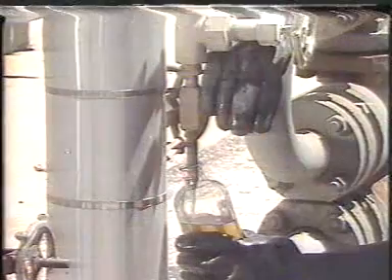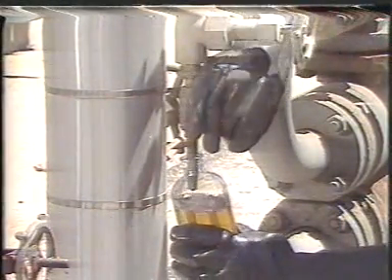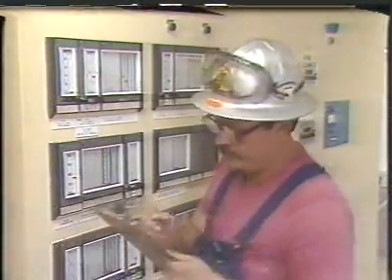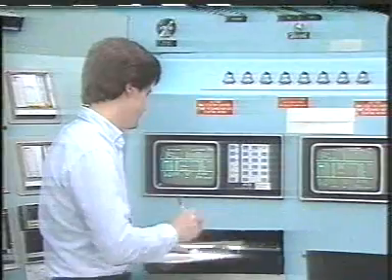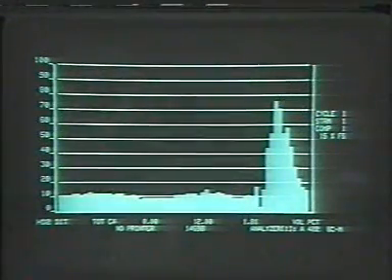During the normal operation of a distillation column, there is a certain set of procedures that an operator should follow. Let's go over these control procedures and then apply them to some normal operating situations that an operator is likely to encounter. An operator is usually responsible for sampling or testing distillation products at regular time intervals. He also checks instrument readings at the same time these samples are taken. On some distillation columns, process analyzers automatically monitor product specifications.